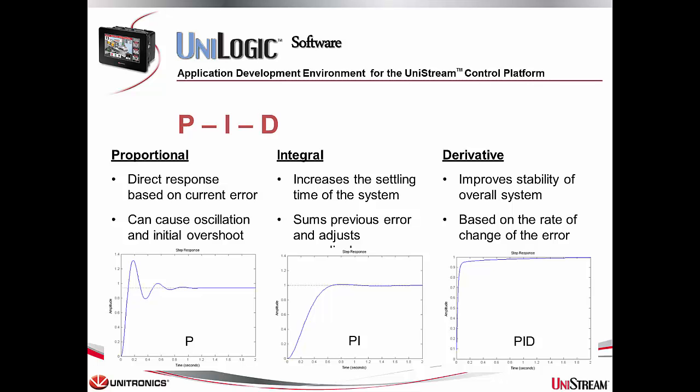Derivative control is implemented to reduce overshoot and oscillations to improve the stability of the system. The action is calculated by the rate of change of the error and produces an output from this calculation. It slows the response of the control value, but results in damping out any oscillations that may occur from the proportional and integral control and compensates for overshoot from these controls. In other words, it will smooth the output.